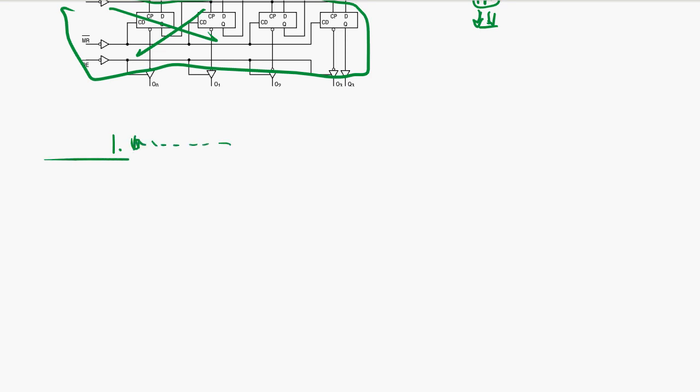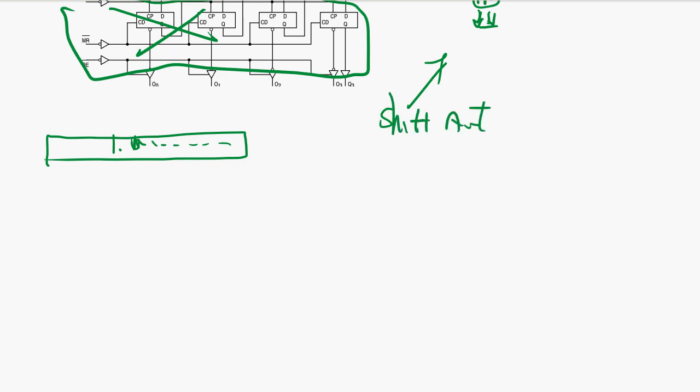and after you bring back to the leading one number, right, this decoded shift amount has to be added to Y, then check overflow or underflow.